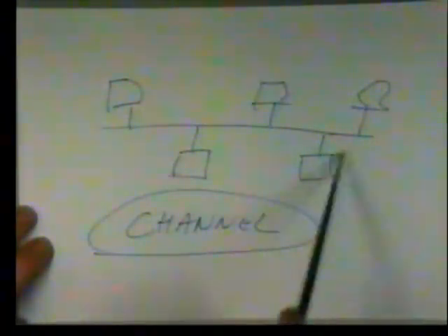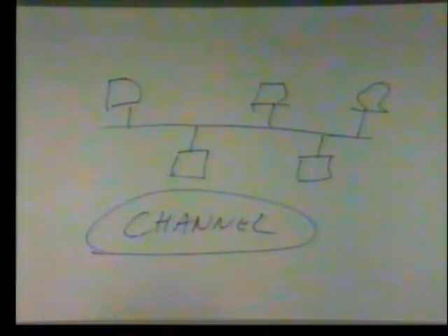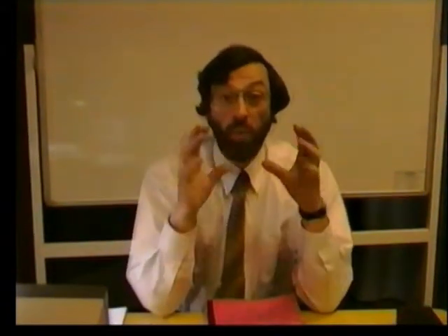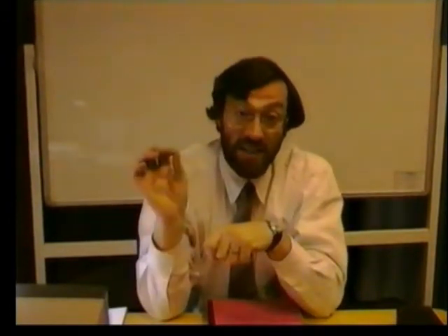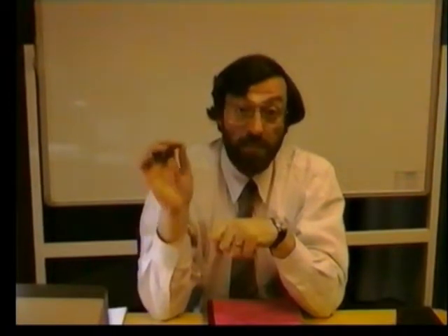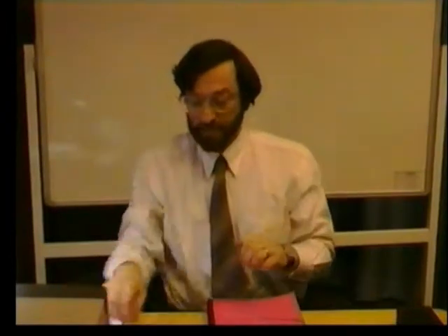A channel is an entity that exists within the network itself, an information block, shall we say. And that means that somewhere one of the nodes must be broadcasting that information. Whatever that information is, something must be the source of it. But every single node, or only those that are interested, are allowed to listen to it. So a channel is an entity that exists on the bus itself. So how does it work? Now let's go back to our picture.